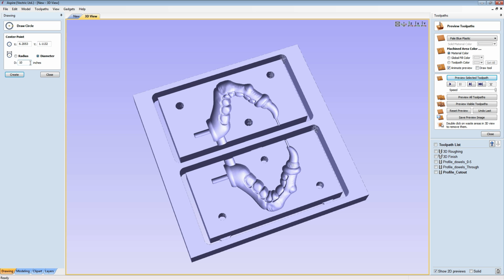I'm going to put the metric value that I want to convert. I'm going to put an asterisk, which is effectively on a computer the equivalent of multiply, and then I'm going to put I for inches, and then I'm going to hit the equals key, and the equals key is what's going to convert that into a numerical value. So 10 millimeters converted into inches is 0.3937.